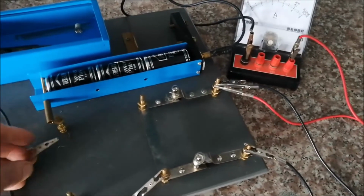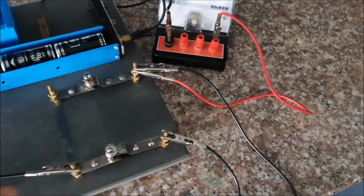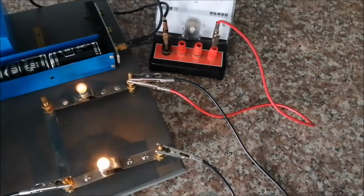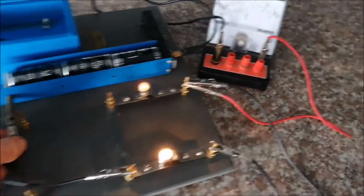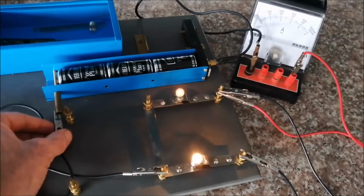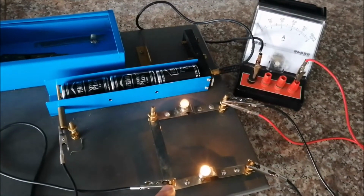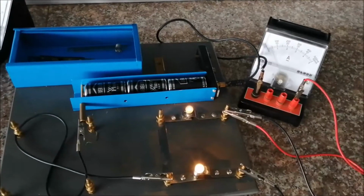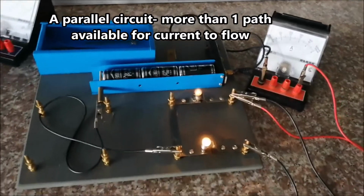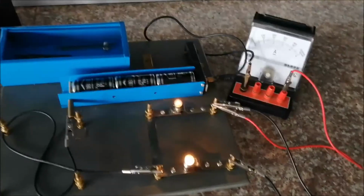And let's look at what happens when we connect the circuit up. Let's just get the lead on. Oh, we've got a break in the circuit, so there we go. Now you can see there, if I just connect the circuit up, that both globes are on, but we have two paths available for the current to flow. So we have what is called a parallel circuit. Okay, so that is the difference between a series and a parallel circuit. You can see here we have an alternative path for the current to flow.